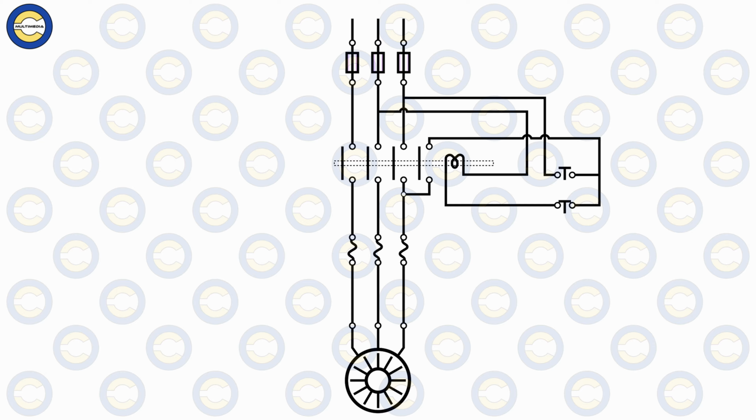To further understand why these starters are so important, imagine that a motor is directly connected to the supply and started instantaneously. It will try to reach full speed instantaneously, that is the final running RPM. It would try to achieve that RPM instantly. But during the starting period, the rotor is stationary and there is no back EMF. So the motor will draw a very high electrical current.